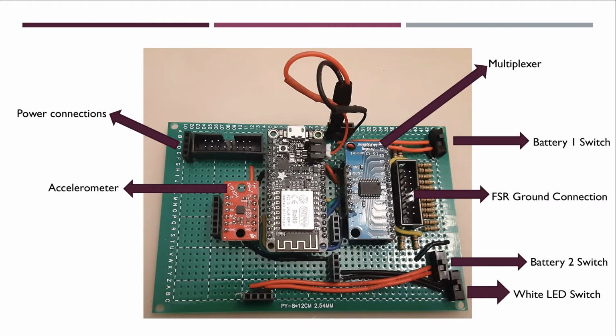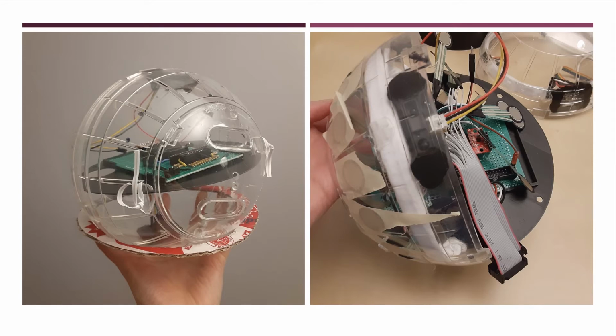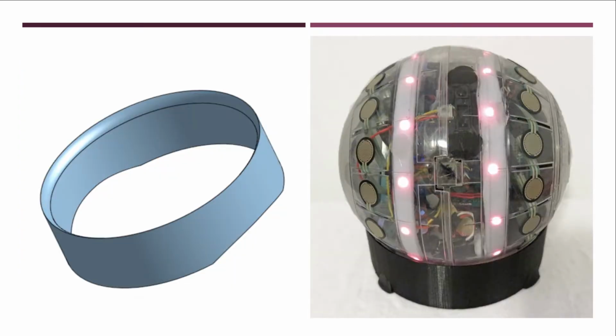And here it is soldered to the circuit board. Since this is the first prototype, I used headers and IDC connectors for all the important parts instead of soldering them in directly. To get all the electronics inside the hamster ball, I 3D printed a disc and used twist ties to secure it inside. And I also 3D printed a little stand for the globe. The stand has a slot so I can slide paint chips underneath to activate the color sensor and LEDs.